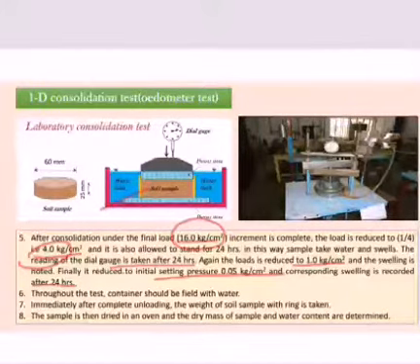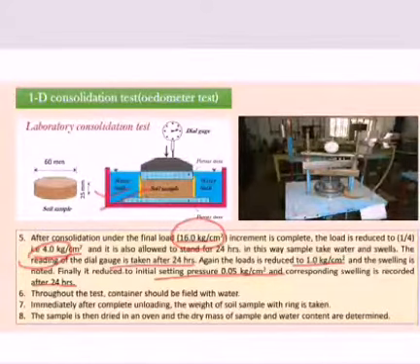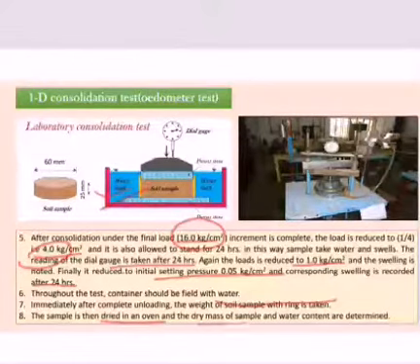Now, throughout the test, the water bath should be kept filled with water. Immediately after completion of the test, the weight of the soil sample is taken, and the sample is then dried in an oven, and the dry mass of the sample and the water content are determined.